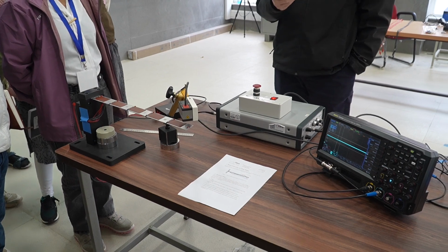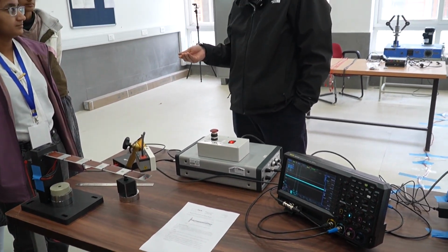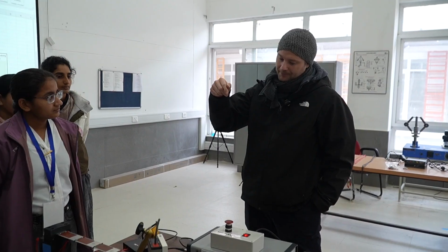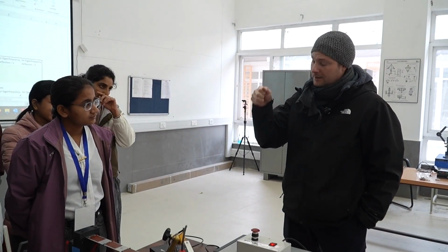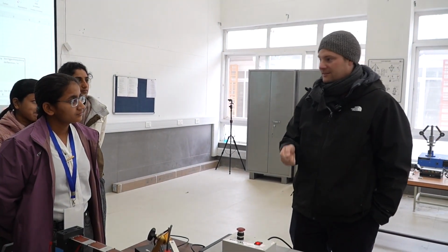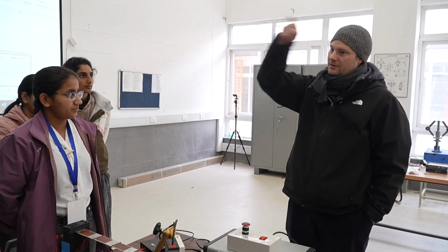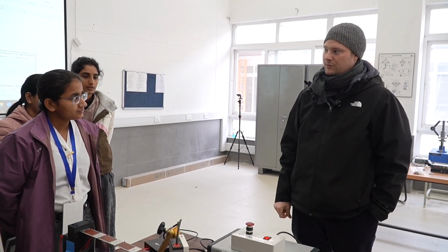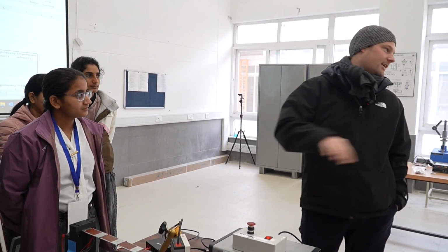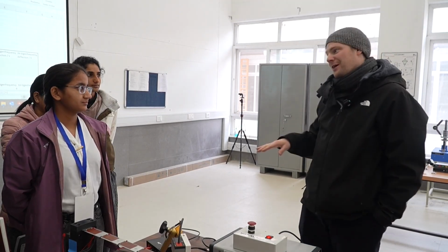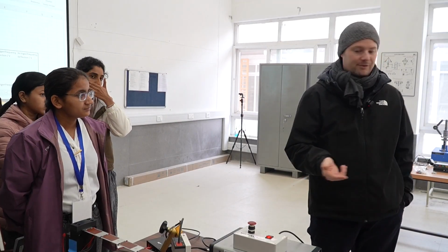They cover multiple frequencies. For example, an impulse, like the Dirac impulse, you know that, right? A Dirac impulse covers all frequencies because it's sharp. If you don't know that, maybe you have to go into that at some other time, but a Dirac impulse covers all frequencies.